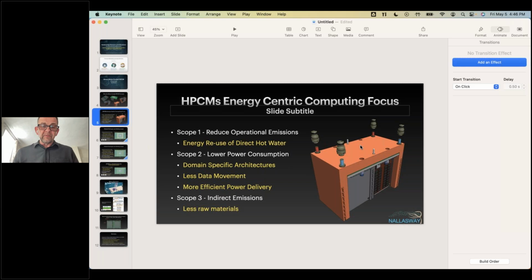So if we all live in houses, right? And we all have walls, and guess what's in those walls? Water and power. So it's saying, why don't we just take that idea, so the water and power is provided by the wall, and it's 48 volts. So it's a super big fat bus bar, or you'd have local power supplies stepping down from the data center voltage levels of 370 volts or whatever that is. I've been talking at the OCP Regional Summit. I talked to Murata. They do the step down to 48 volt power supplies. So they're in our work group, just seeing how they could build that into the wall, and we could get efficient power delivery. So yeah, the 48 volts comes in extremely efficiently, and then you step down from there. Makes sense. Okay, thanks.